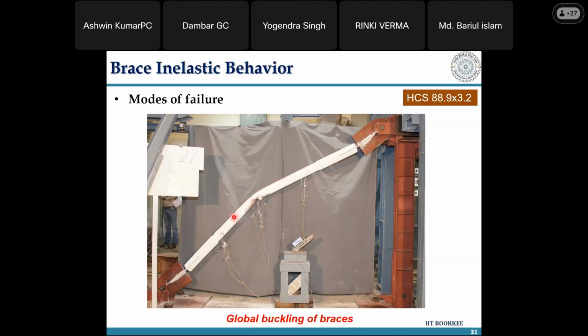If the distance between the brace and the casing is very low, that as soon as it touches the casing, the first mode gets stopped and it goes into the second mode. And if the gap between the restrainer and the core element is such that you can make it go into higher modes of buckling, then n square pi square will keep increasing and the peak value that it can achieve is the yielding in compression value.